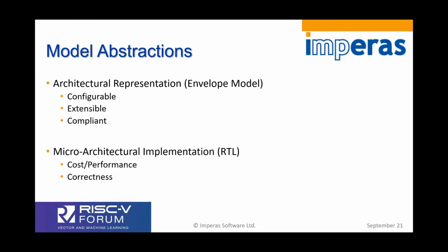When designing a device to conform to a given specification, the responsibility of the implementation team is to produce a design which fits within the functional specification, but more importantly, meets the design goal challenges, whether that be area, performance, power, or any other goal. Our desire is to use the architectural model to ensure that during the design, test, and continuous integration of the RTL, the functional representation remains within the legal constraints. You can think of this as a highly configurable and powerful assertion and protocol checker.